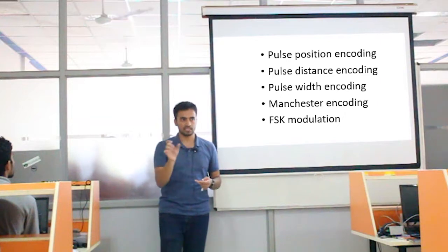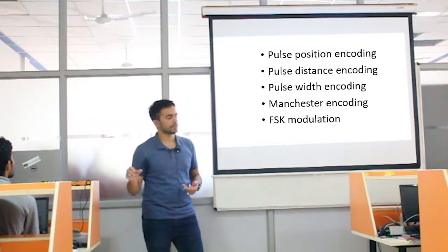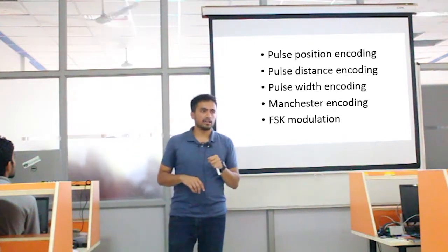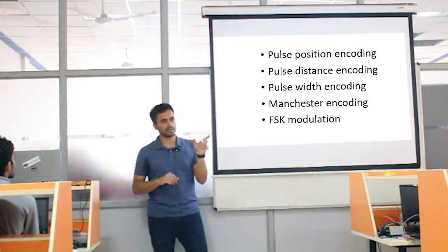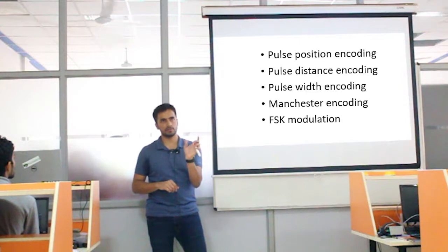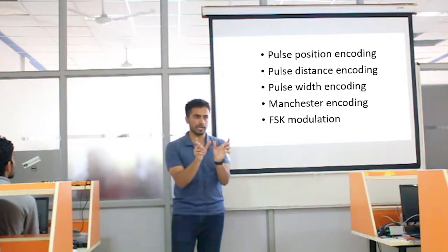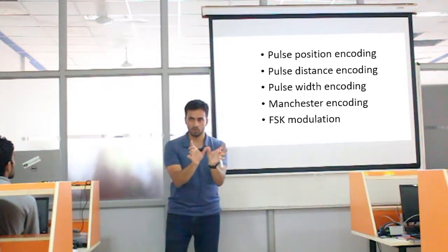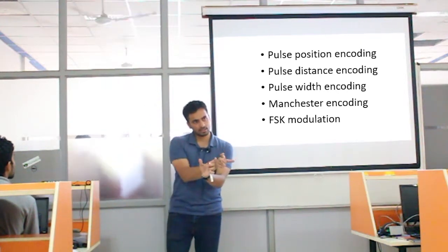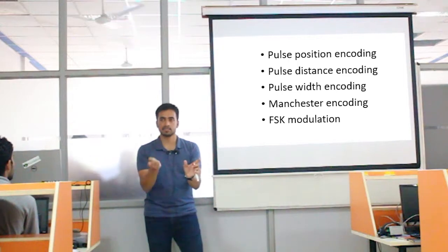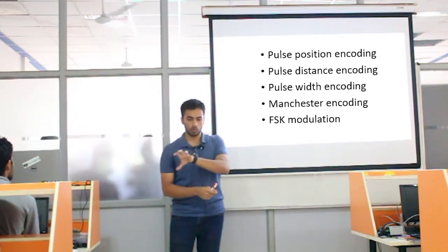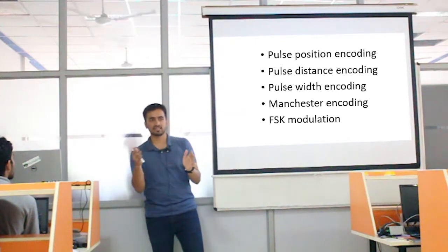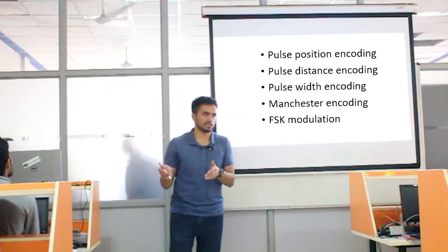So this is pulse width, where the width of the pulse is changed continuously. And Manchester encoding, this is a popular encoding method. What is done is, you do nothing for the first, say, 5 milliseconds, and then modulate for the next 5 milliseconds. So nothing, modulation, this is a 0. You modulate first, do nothing for the next 5 milliseconds, this is a 1. So based on whether there is a pulse at the beginning or towards the next half determines whether it's a 1 or a 0.